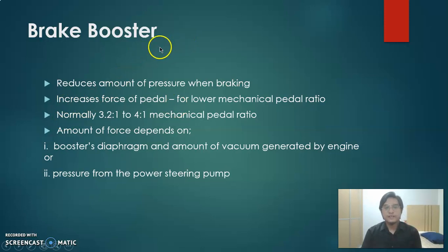So the brake booster is an additional component. The brake booster comes in two types. There are vacuum brake boosters, which usually use the vacuum generated by the engine and the diaphragm, while the second one is hydro boost. Hydro boost uses the pressure from the power steering pump. The functionality is the same. It's to reduce the amount of pressure needed when braking.